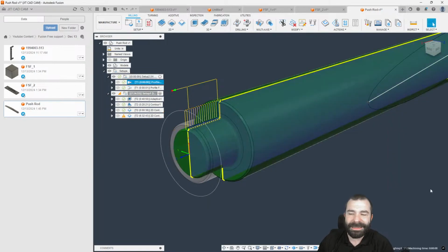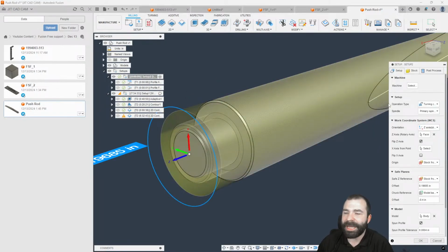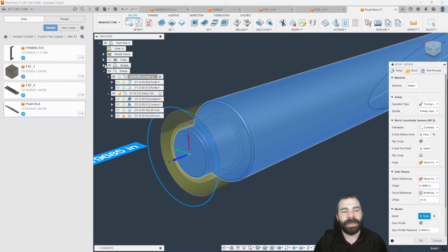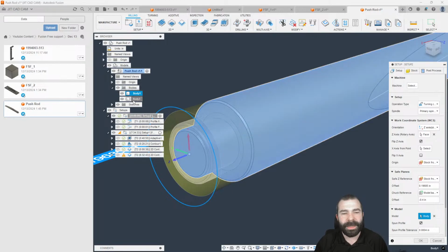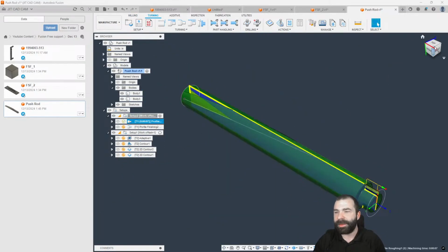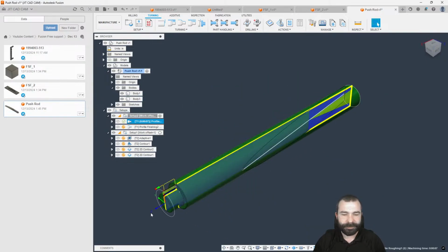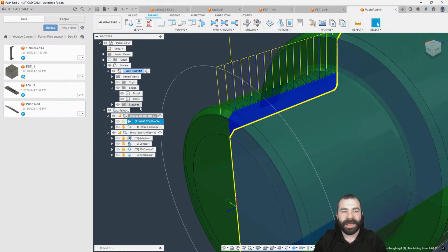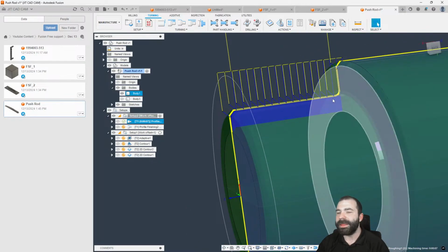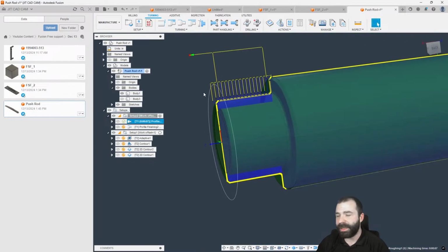So what I would need to do on a lathe is actually place my model in my setup, right? So again, I'm going to go back to my setup. I'm going to pull that second body in. Again, now regenerating that tool path. And what you'll notice is we're now machining that larger body, which I'm going to turn off temporarily. So we're avoiding that area and then still machining everything else.